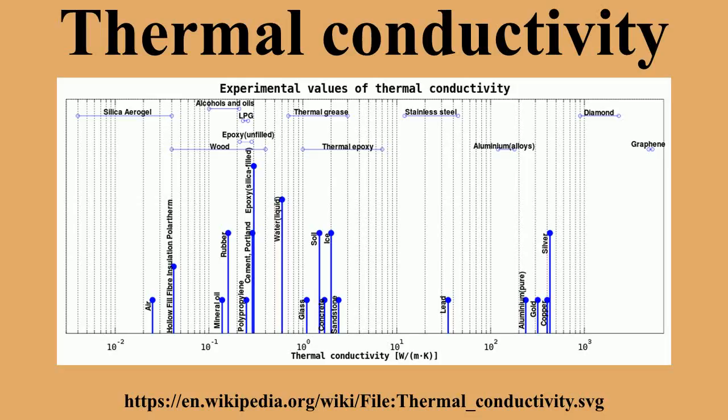an animal's skin. Light gases, such as hydrogen and helium, typically have high thermal conductivity. Dense gases such as xenon and dichlorodifluoromethane have low thermal conductivity. An exception, sulfur hexafluoride, a dense gas, has a relatively high thermal conductivity due to its high heat capacity. Argon, a gas denser than air, is often used in insulated glazing to improve their insulation characteristics.